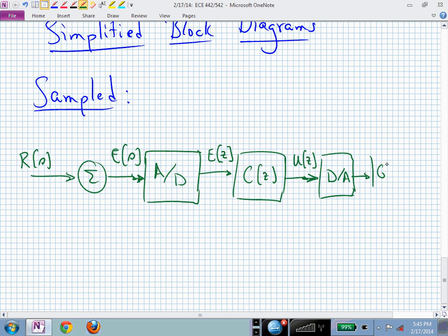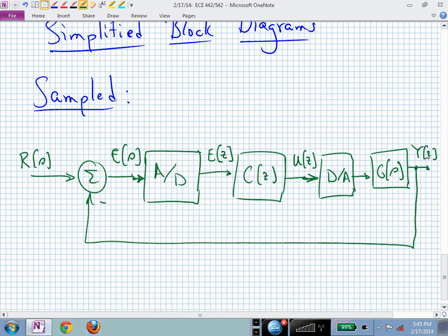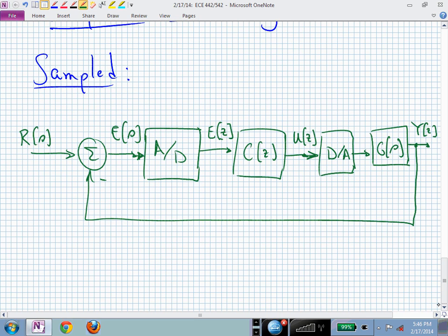You can see that I'm actually neglecting some of the other pieces, the disturbance piece, etc., and maybe I will forget what's in the feedback path, but now we have a sampled block diagram, this now being a sampler, and this getting us back from a discrete sequence into an analog formed signal. That's what we will say is a hold sequence. Yeah, or hold. Thank you.